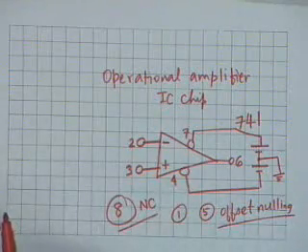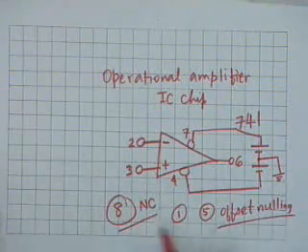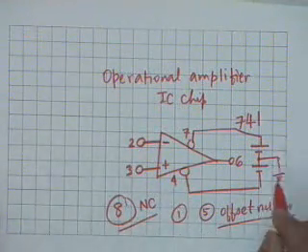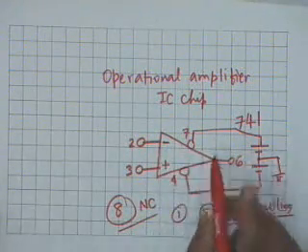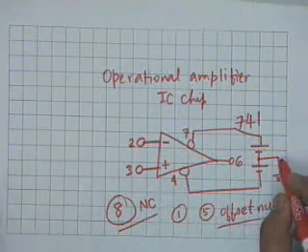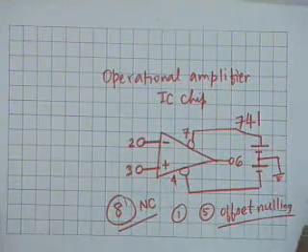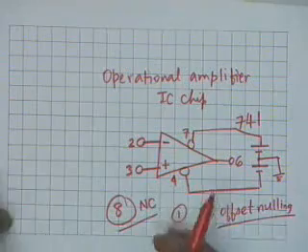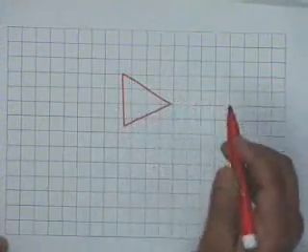Pardon me? So does it provide a port or a terminal? It provides a terminal, but between 8 and the power supply ground, it provides a port. This is obviously external. The 741 chip provides no ground. The ground has to be provided externally by means of the power supply. So the reference is set outside the chip. All right. So this is 741.